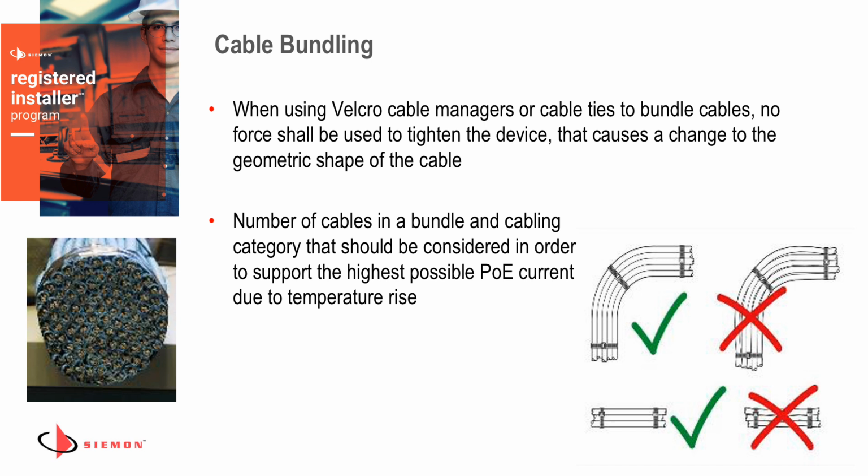Now, when it comes to cable bundling, most installers do a really good job of using Velcro style cable ties or tie wraps to ensure that the installation is organized and looks good for the end user. The real limitation there is to just ensure, again, you're not deforming any of the cables. And honestly, that's why most people use Velcro cable ties as opposed to plastic ones. Plastic ones can be over tightened and cinch the outside cables, which is not good. With Velcro, it's very difficult to over tighten those to the point where you're deforming any of the cable jackets, so it's usually not an issue.